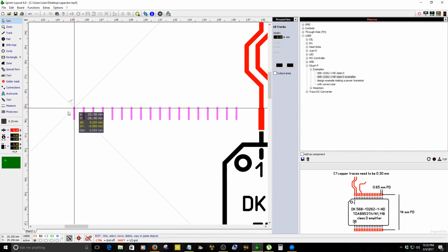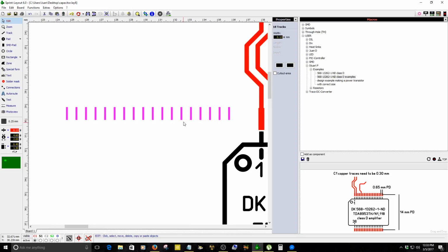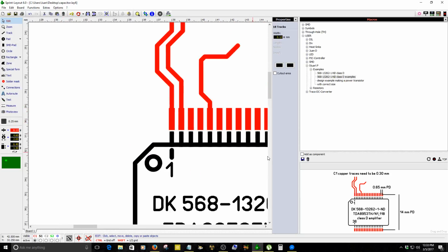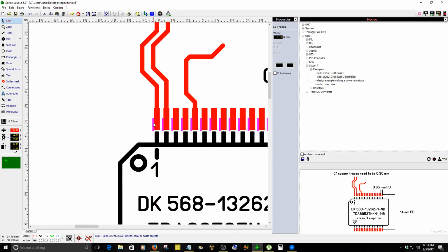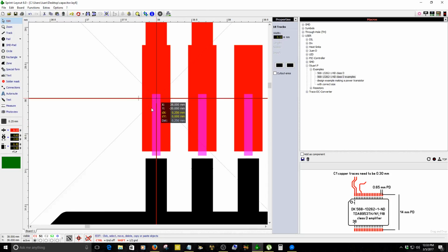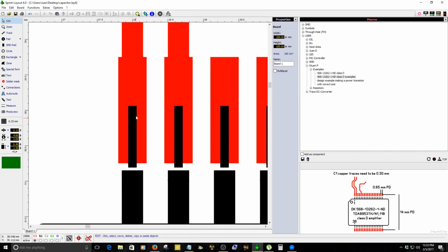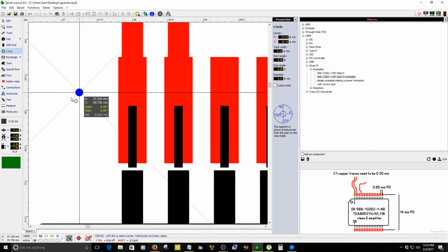This is the wire of the integrated circuit. So we're gonna place it here. Hold on, give me a second, guys. As you can see, that's the area that is going to be soldered. You know, there is one technique. You put some flux, and then you just drag your iron. It's gonna solder everything automatically, really fast. So it's gonna have like shiny balls. Sounds funny, but anyway.